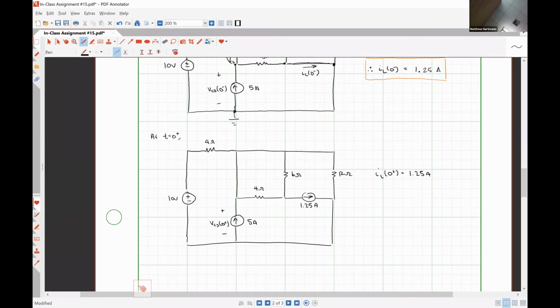So this looks at a minimum reasonably complicated. So I would suggest that since we are determining a voltage, we may want to use nodal analysis because that will give us a voltage directly. So I'm going to choose my bottom node as my reference node again, just because it's convenient. So I have this node, which is VCS. And I'm going to label my nodes a little bit better this time just because this node's going to be a big one. And we're going to have to pay attention to what's going on when we do our nodal analysis.